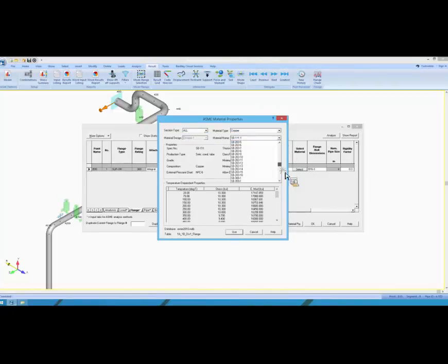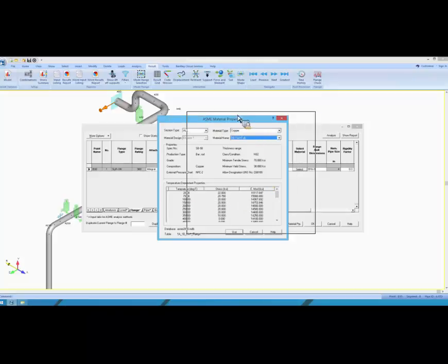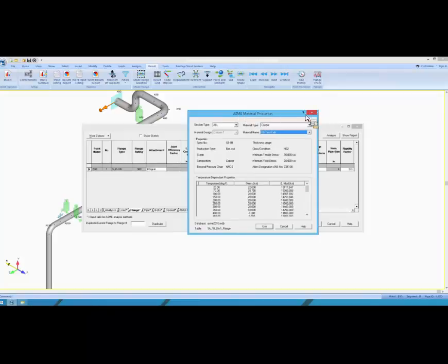So at the end, I can see an SP Tech Talk material already added with the properties that I defined in that. Like you can see the 22.0 stress at 20 degrees centigrade, which I just entered. So that's how you can customize the input data as well if you want to.